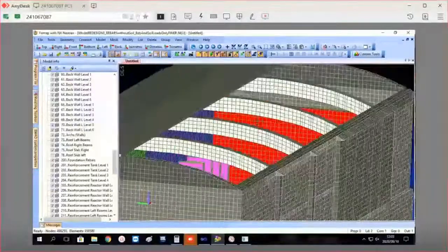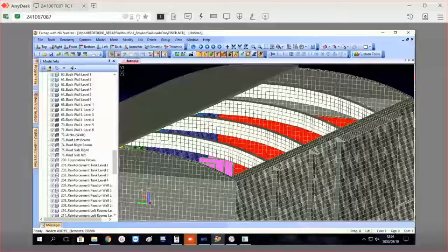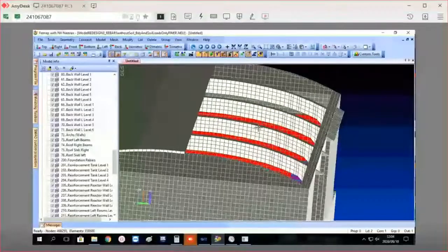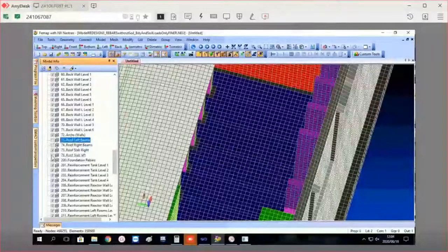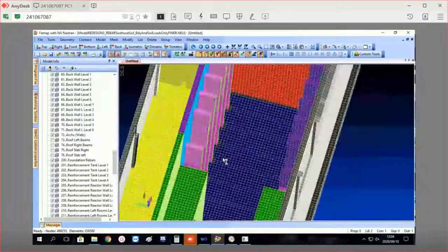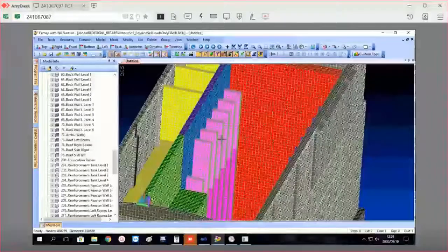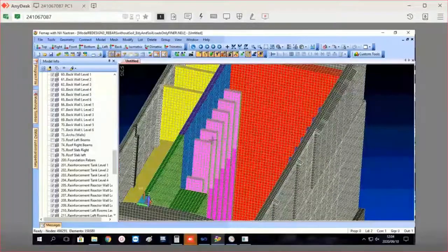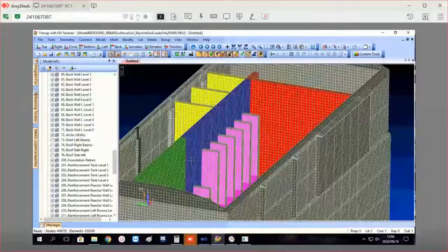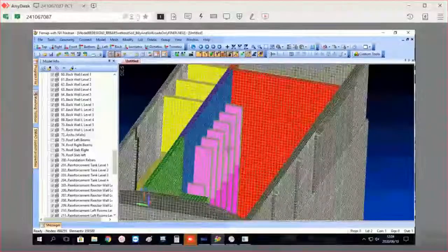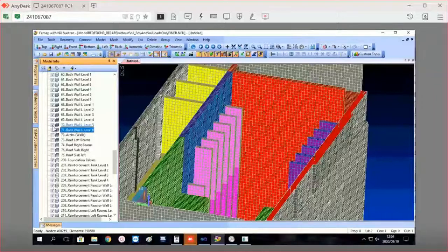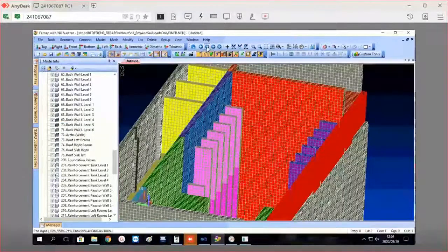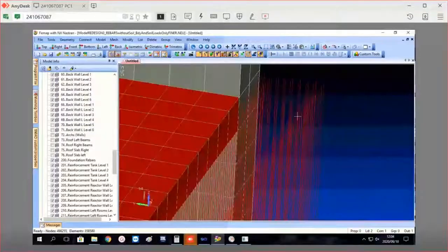Nuclear Reactor Building in new scale, 70 meters long, 30 meters width, and the height is more than 35 meters. As you can see, this is 2 meters tall beams, and inside here you can see the area and the pool of the reactor building. So let's remove the roof completely so you can see the model. So this model has 2.7 plus million embedded rebars, 180,000 plus hexahedral elements. Okay, so if I remove the walls, let's say, and the arcs, if you zoom in here, you will see the embedded rebars. Can you see them?